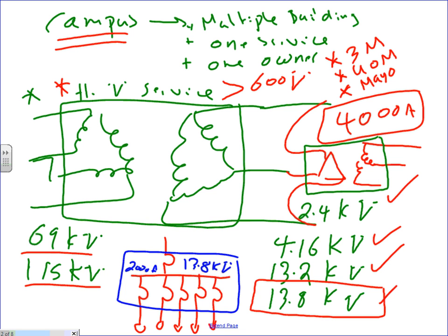Can you guys see that? You bring the transformer to the switchgear like this, 2000 amp, typical 13.8, and then each one of these feeders will be going to feed a building. So high voltage. Again, where would you encounter this? Big campuses, big industrial plants, refineries, oil refineries, all these campuses that need a lot of power. Some of them have their own 13.8 system that they distribute.